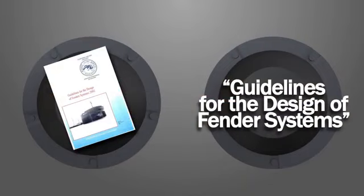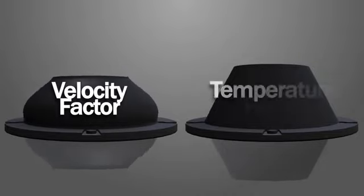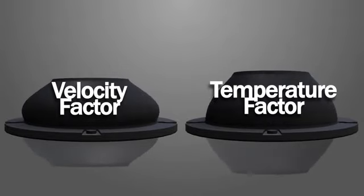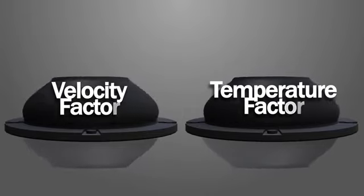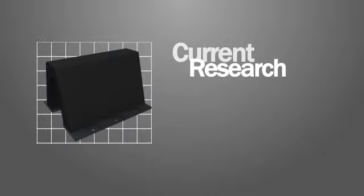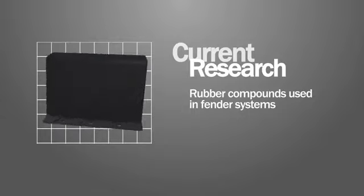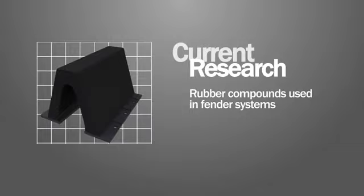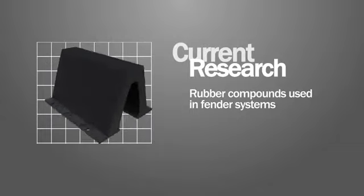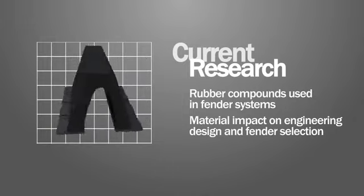PIANC's 2002 Guidelines for the Design of Fender Systems highlighted the importance of velocity factor and temperature factor in the design and selection of fenders, and introduced guidelines for reporting and calculating both. But current research into the changing properties of rubber compounds used in fender systems and the move towards non-traditional fillers mean velocity factor and temperature factor are now highly likely to have a material impact on engineering design and fender selection, as well as further implications for the design of other wharf infrastructure. First, let's take a look at velocity factor.